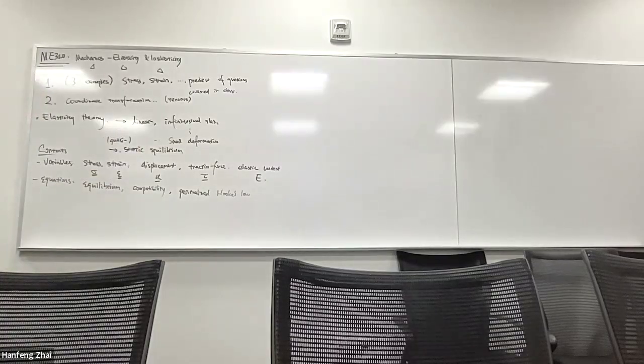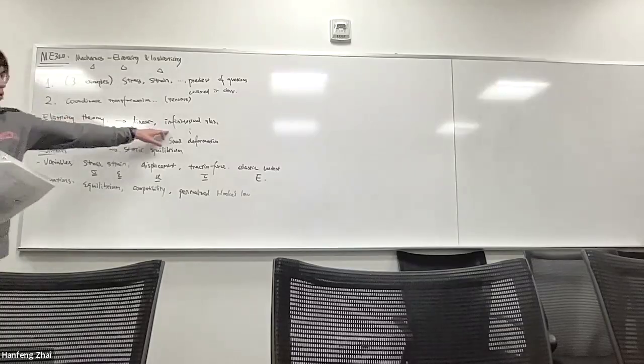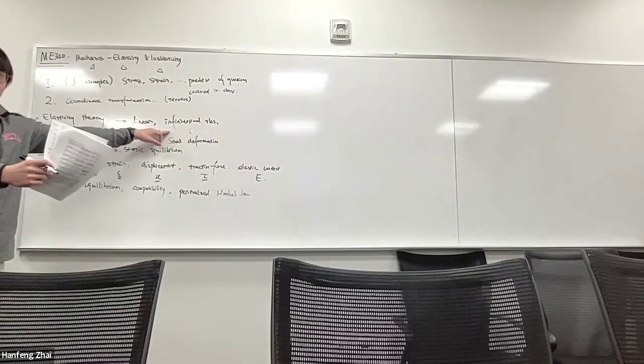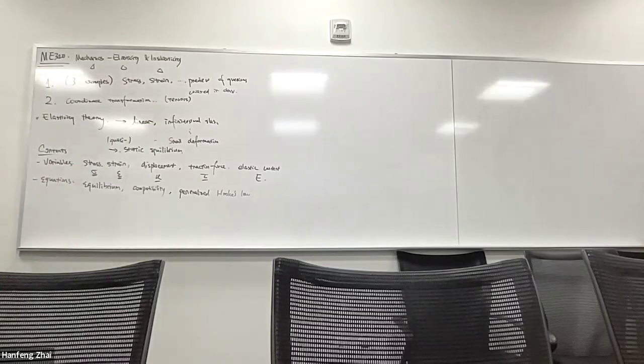And you're gonna cover all of these in this? But under infinitesimal elasticity, we don't distinguish reference and current configuration. So yeah, that's also correct. There's just very infinitesimal small motion, which you can call we define the displacement. We define displacement as the original, so small x and big X. In this class we don't distinguish small and big X, only when we define displacement, and when we later move to displacement, we assume the current and reference configuration are the same.